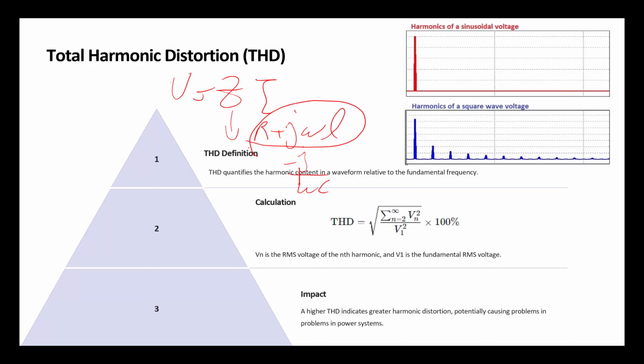What does more loss mean? Higher temperature. Our main problems. These are the reasons that we don't like harmonics and we have to get rid of them. These are why they are considered a power quality issue, because they introduce other frequencies into a system, mess up our applications, and add more losses.